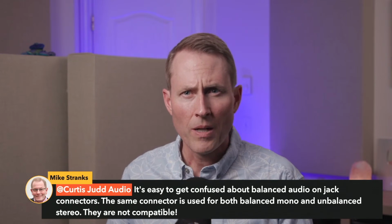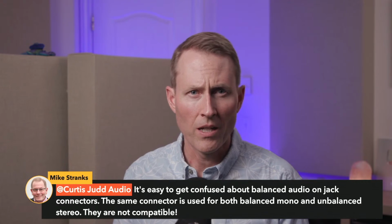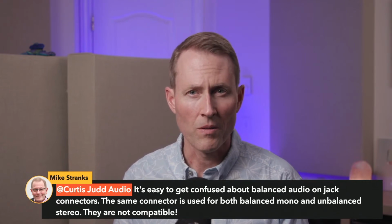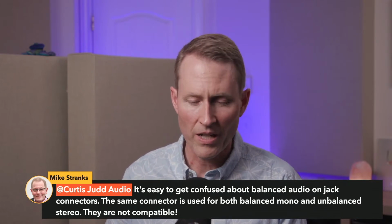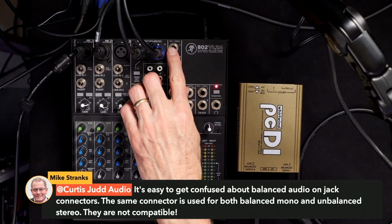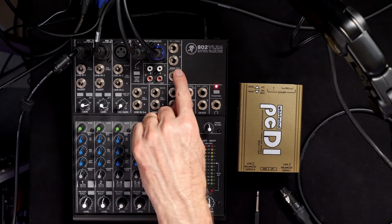It's easy to get confused about balanced audio on jack connectors. The same connector is used for both balanced mono and unbalanced stereo. They are not compatible. Yes, you'll want to read your documentation or read the face of the mixer, which will generally tell you. And in fact, if we go to the overhead here, you can't necessarily see it, but this says balanced, unbalanced, left and right main outputs here.